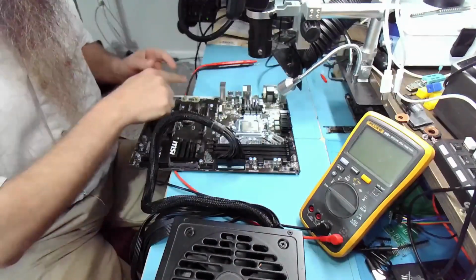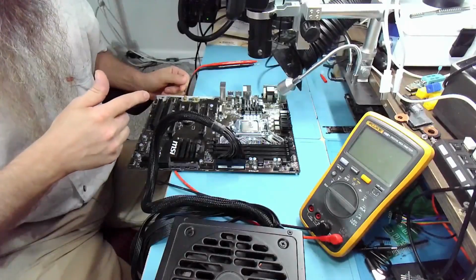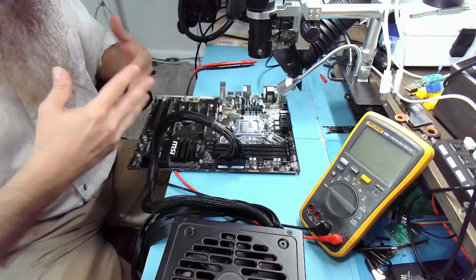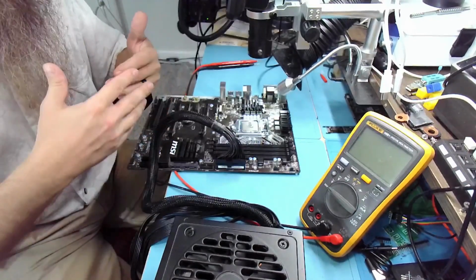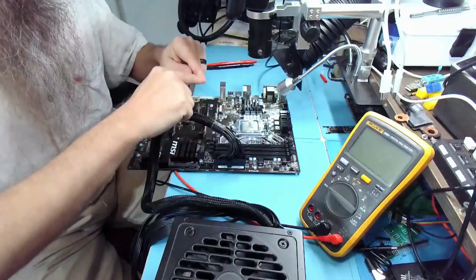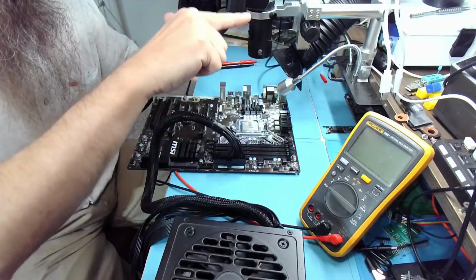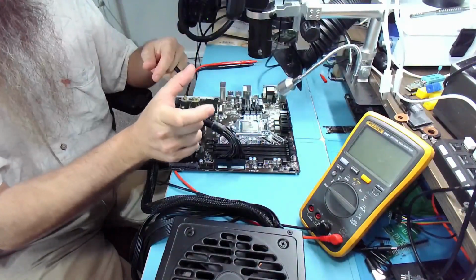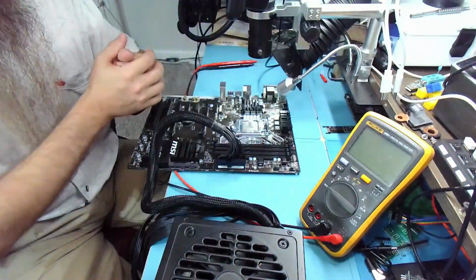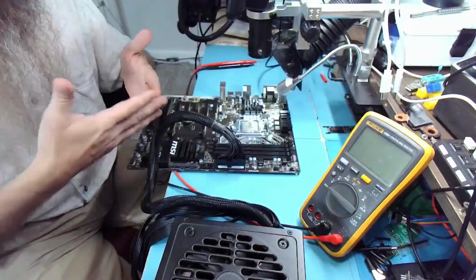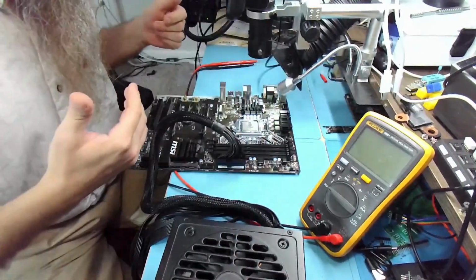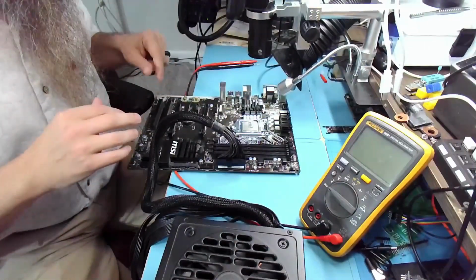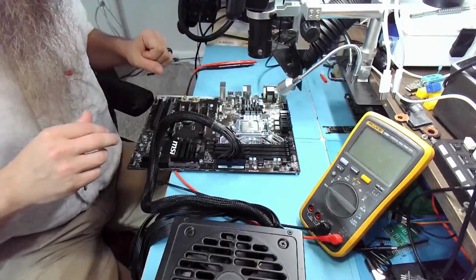And even though I don't see the current sensing resistor, there's another way the board or SIO can assess whether there's an abnormal current draw, via timing. How long does it take from 0 volts to 1.2 or 1.4 to be reached? If the time is too long, that means we're grabbing too much power and it turns off. It could make sense. So this test will also hopefully eliminate the issue with the CPU.